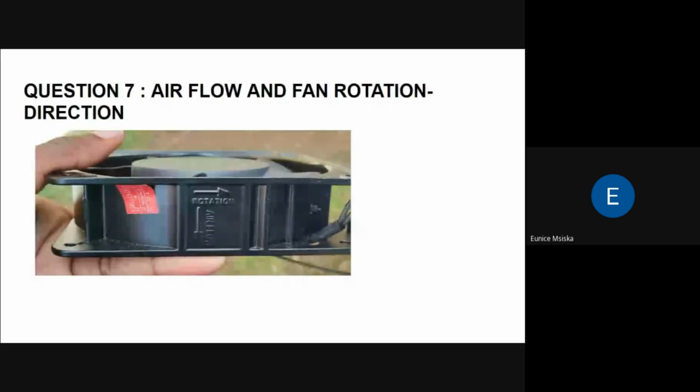When you realize you have a clogged fan and are about to replace it, make sure you have taken note of the connecting wires and the position of the fan and the fan guard. The fan has an airflow directional arrow on the sides that shows the direction in which air is supposed to flow. Make sure this arrow is directed away from the compressor when installing the fan in its place.